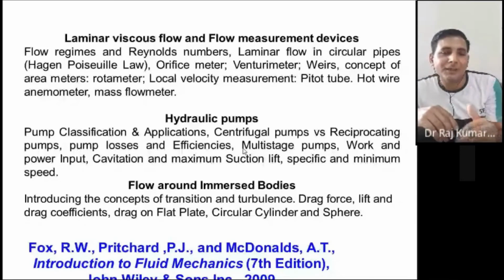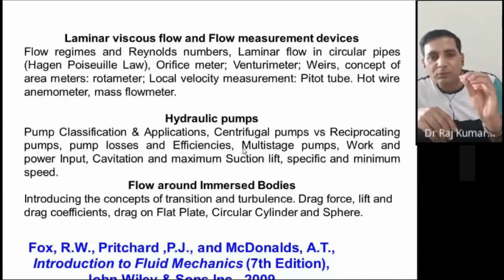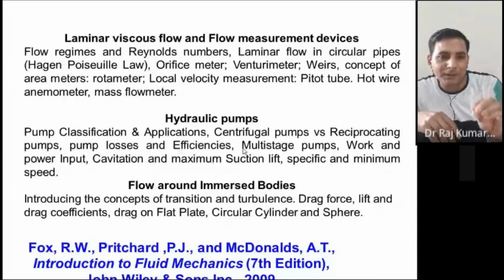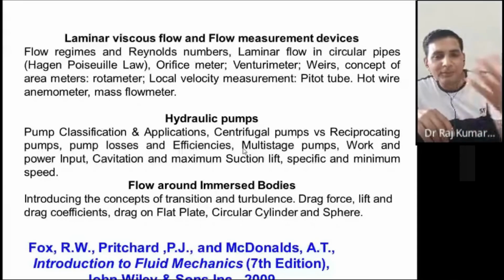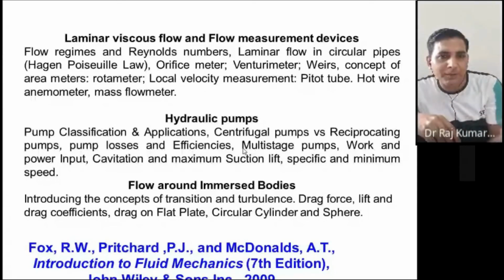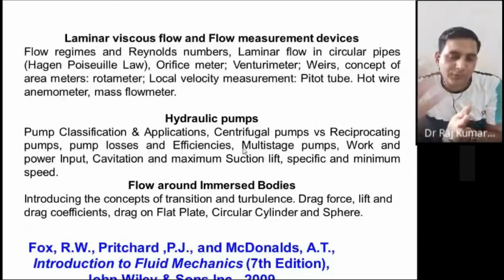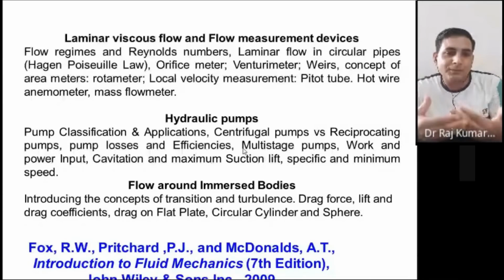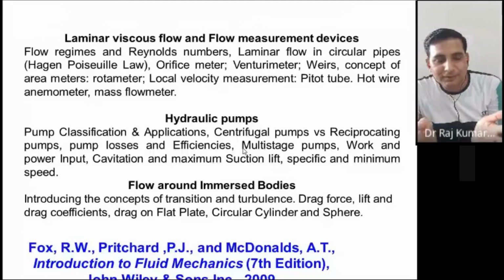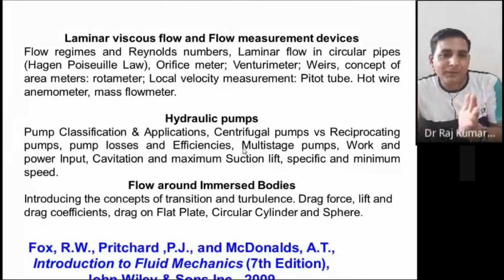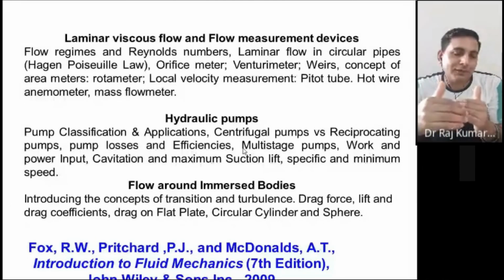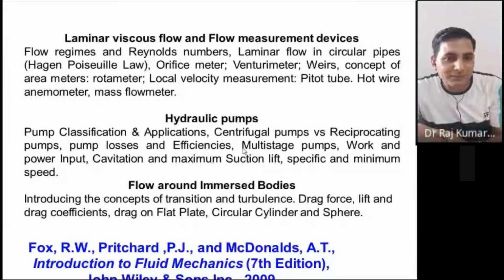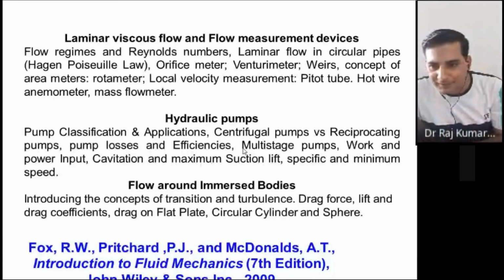That happens only because there was no water to suck in the pipeline, and you were turning on the pump. So you are continuously giving energy to the pump, and the pump is not delivering energy to the fluid. Whatever energy you were giving to the pump was just being used to raise the temperature of the pump, and finally it burned out. So you should not turn on the pump when empty. You should have water there first, so that it can transmit the energy, right?